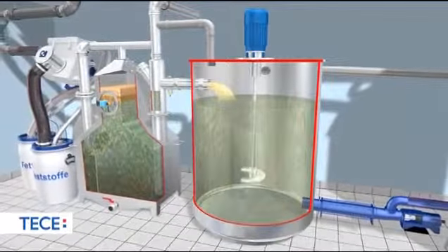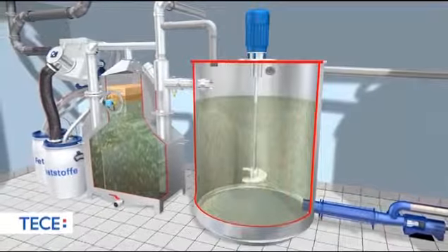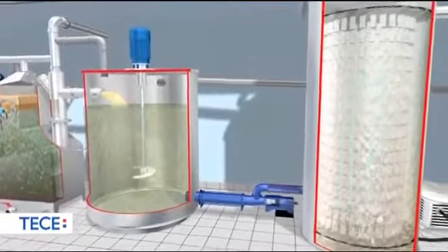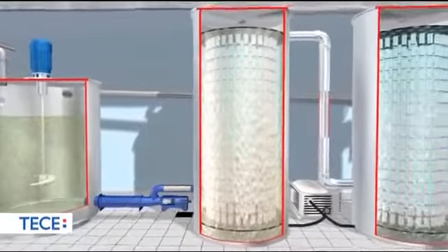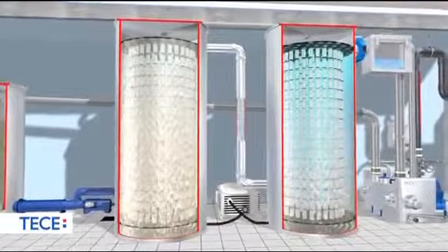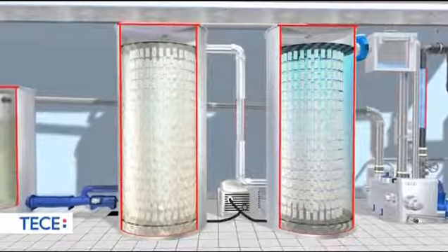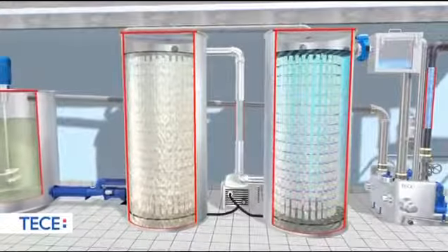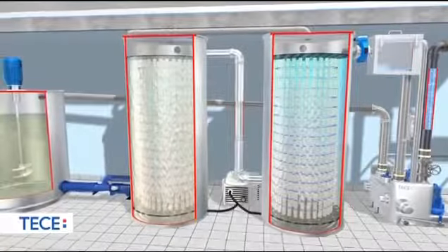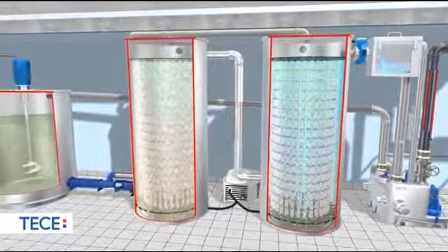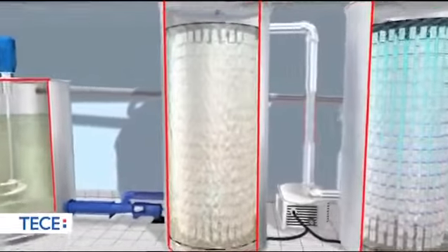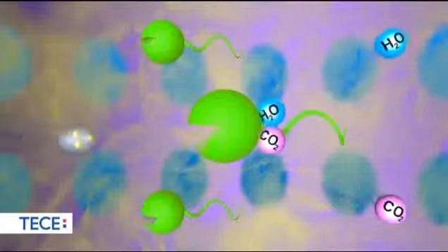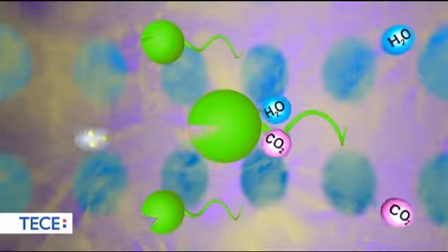Once the liquid in the buffer tank reaches a certain level, wastewater is discontinuously pumped into the two bioreactors or fermenters downstream. Bioreactors 1 and 2 contain a substrate which has been seeded with special bacteria. During the second step, the actual biological decomposition process takes place. The filling serves to increase surface area so as to nurture development of a microbiological system. A biofilm is formed by the bacteria cultures on the surface of the filling.